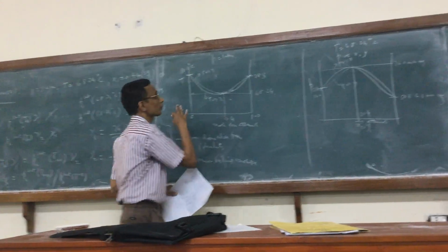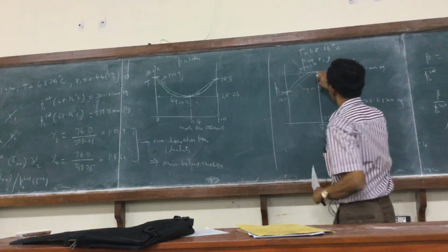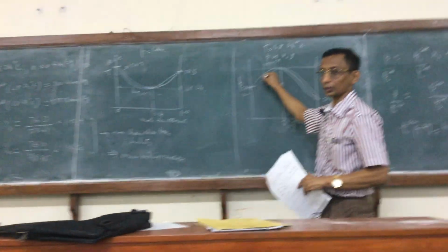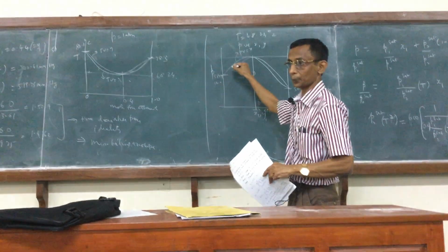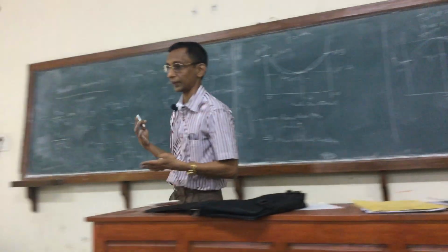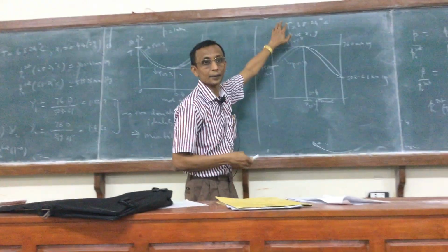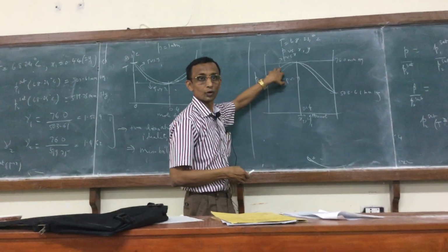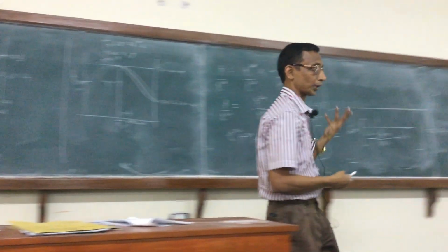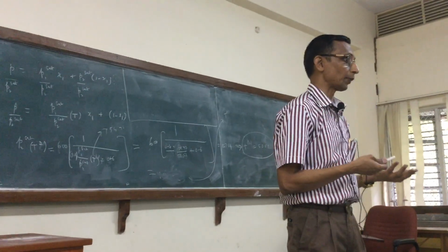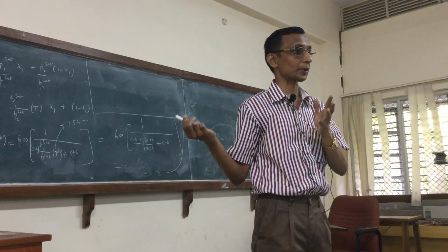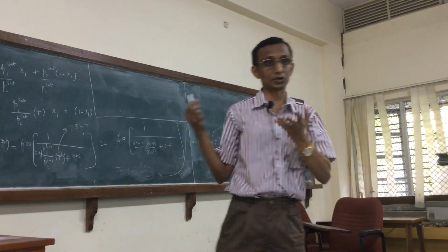Because you can easily do some calculations here to find out the bubble pressures, and for the bubble pressure we know the explicit expression. For instance, if we want to construct this diagram, T equals 68.24. So temperature is fixed. I can either choose to calculate the bubble pressure or the dew pressure. Obviously, I will choose the bubble pressure, because once I choose the bubble pressure, the dew pressure calculation is automatically taken care of.